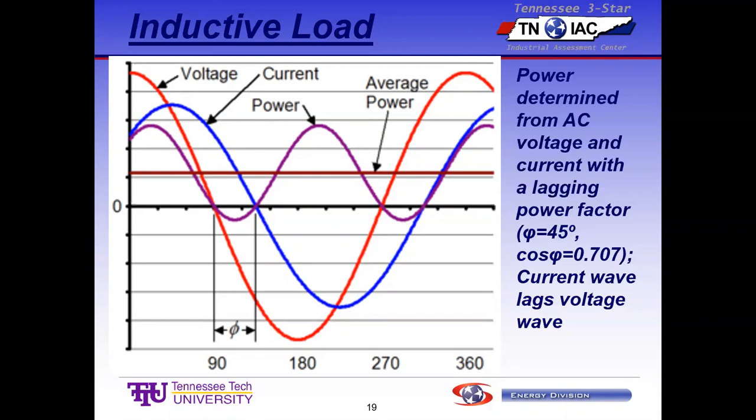And so they're checking those utilities. They're out to scalp as much money as they can from you, so they're looking at all this stuff. On the lagging power factor, which is at the peak demand, they give you a certain amount of cushion before they start penalizing you. It depends on the rate.